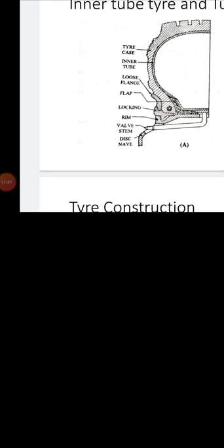What are the benefits? That is the air retention, safety, ride comfort, tire cooling, wheel assembly balance, and obviously assembly of tire on wheels. So these are the advantages of tubeless tire over the tube tire. Air retention means in tubeless tire, the inner lining does not stretch unlike ordinary inner tubes, and the cover wall itself resists air passage, therefore air loss is very much lower in that case.